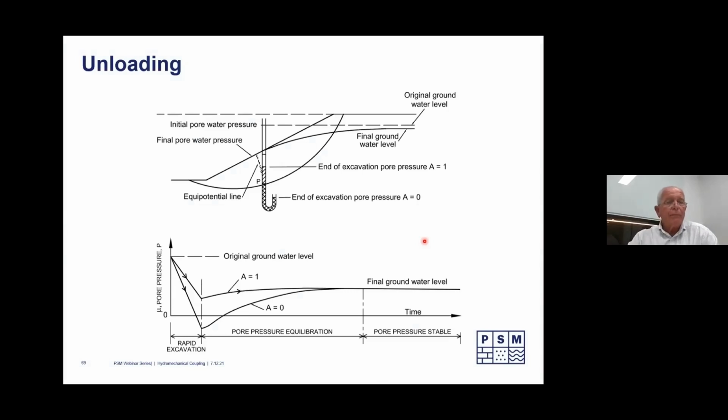Lastly, we're going to look at unloading. We're getting very close to the end now. And here we've got an example where we might actually have ground surface here, an initial water table here, and we dig this slope. We excavate it. And we've got another piezometer in here, and depending on the pore pressure coefficient, which measures the response of the water in the material to loading or unloading, we can have various pore pressure responses in that.